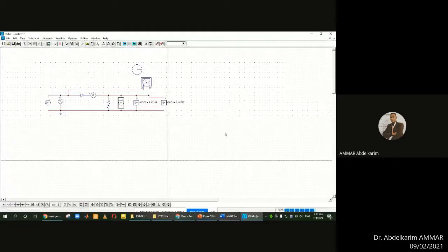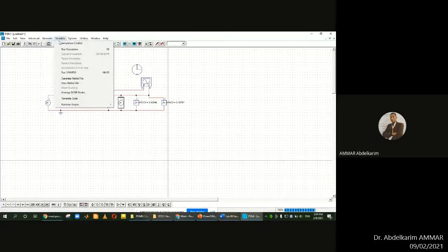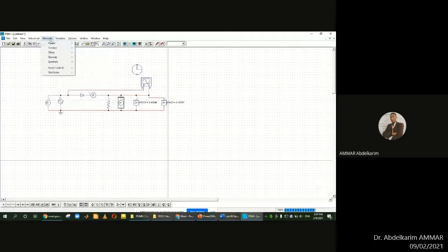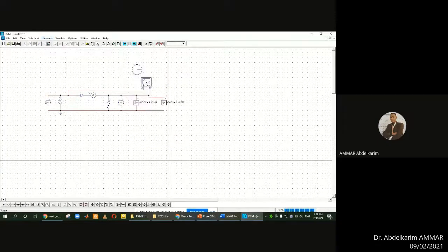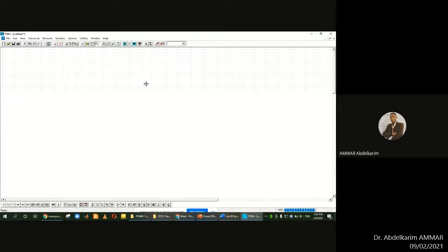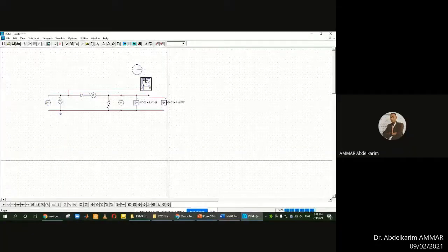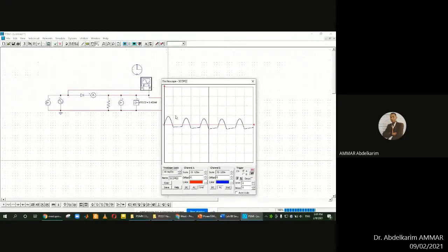We have also seen how we can display different signals with the oscilloscope. We have a one channel oscilloscope, two channels oscilloscope, and also a four channels oscilloscope, which we can bring from other probes. The scope works the same as a real oscilloscope. We have the time division, the voltage division, and the coupling. For example, here we choose DC with AC coupling, and we have 2 channels.